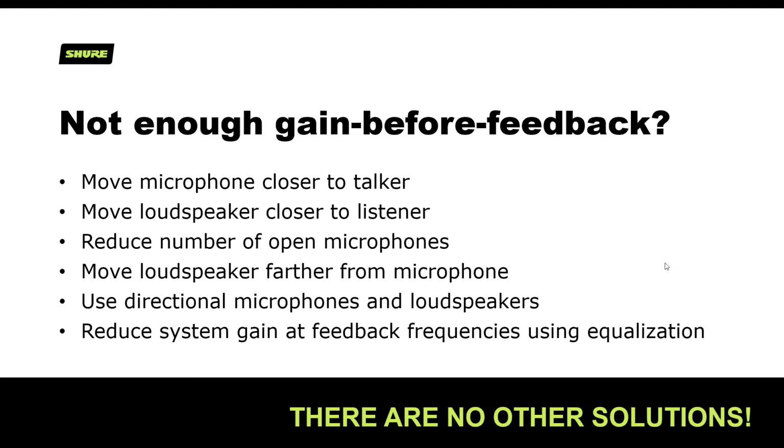Move the loudspeaker further from the microphone. And the reason this is further down the list is because that's not always practical, right? If the loudspeaker is fixed in place, you might not be able to change this. But if you can, it's a thing to try. Then think about using directional microphones. If you're using Omni mics that are handhelds or Omni gooseneck mics, maybe switch to something that is directional, or lavalier mics. Think about cardioid pattern lavalier mics, and also directional loudspeakers aimed appropriately.